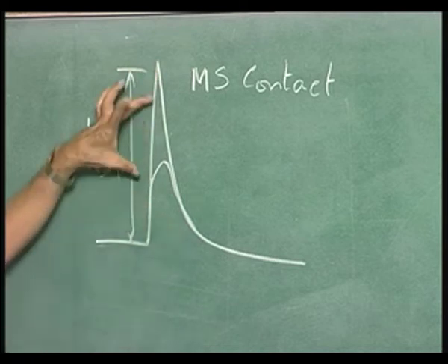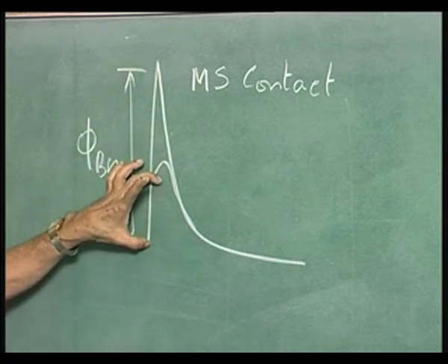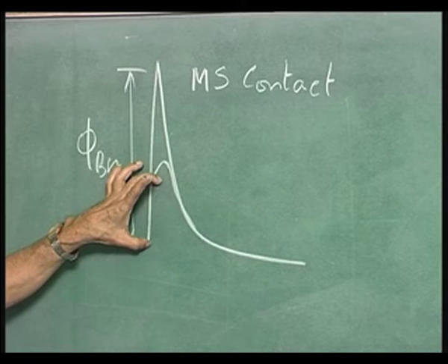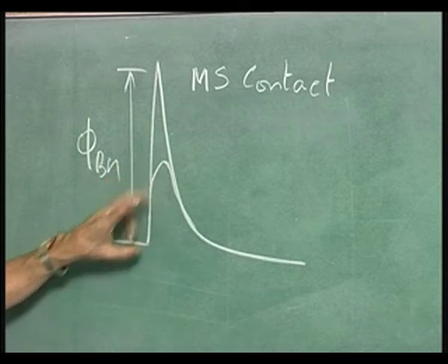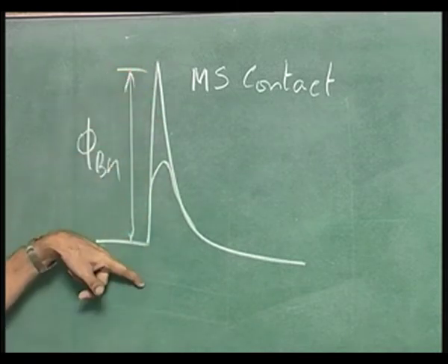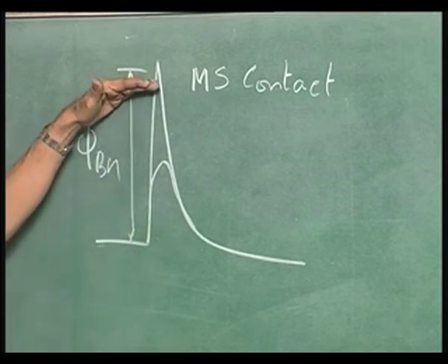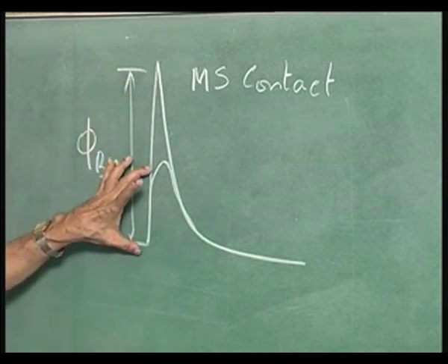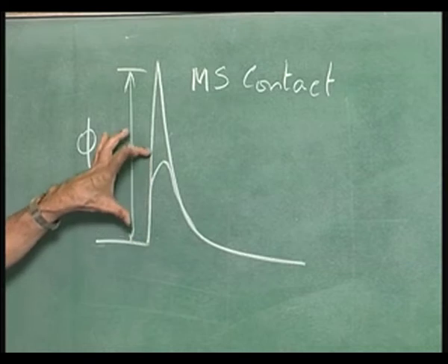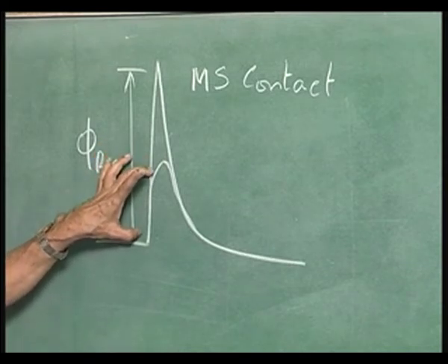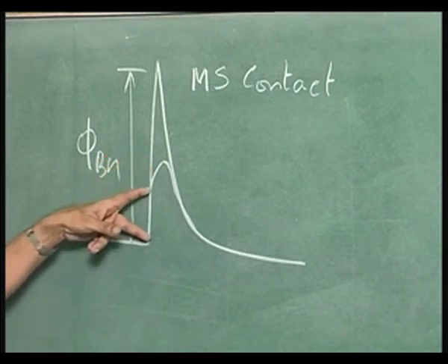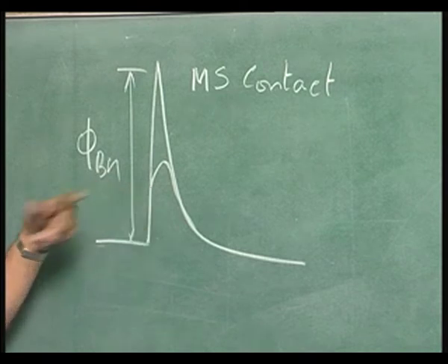Make this heavily doped, that is reduced quite a bit. How much it is reduced depends on doping and also a combination of these two. So, if this is high already, it becomes difficult to reduce it to the extent that you want. The moment it is not reduced to very small values, it has a finite barrier height, and it looks as if it is a large contact resistance.